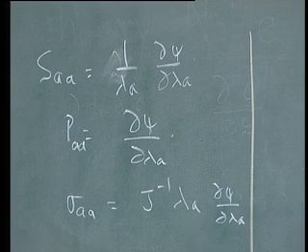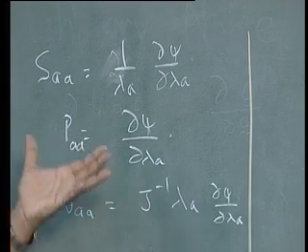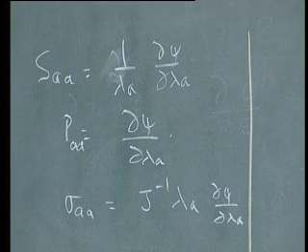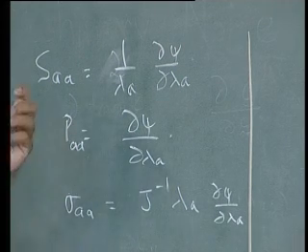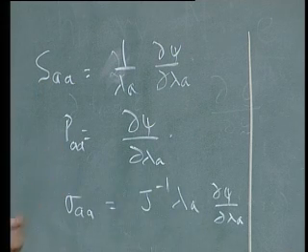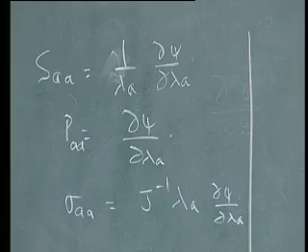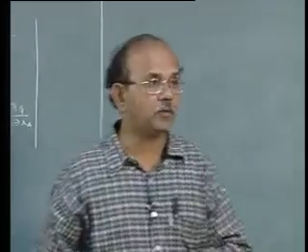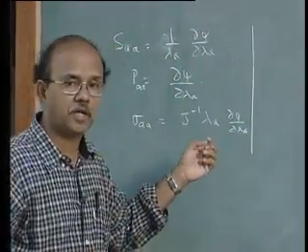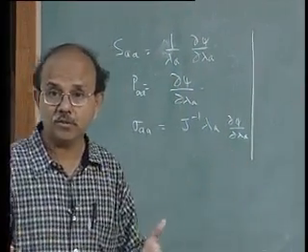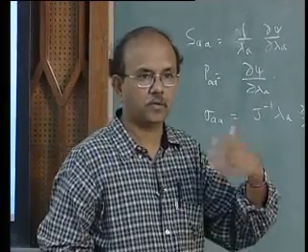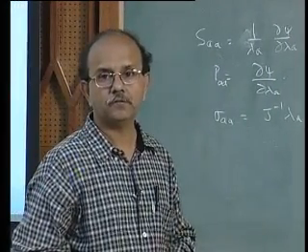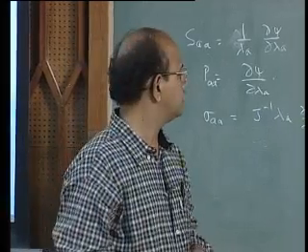ultimately, when we left in the last class, we said that the different measures of stresses, for example, the second Piola-Kirchhoff stress, the first Piola-Kirchhoff stress, the Cauchy stress, and so on, can also be written in terms of stretch. Note this carefully, that stretches are nothing but the square roots of the eigenvalues of C and so on.